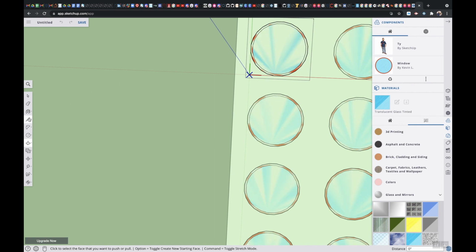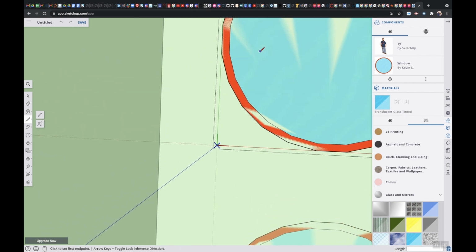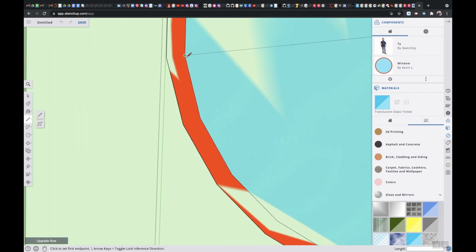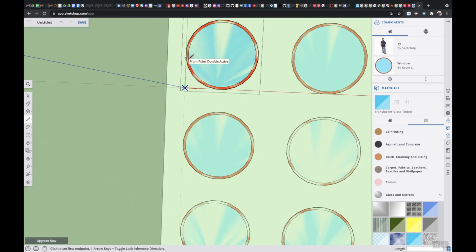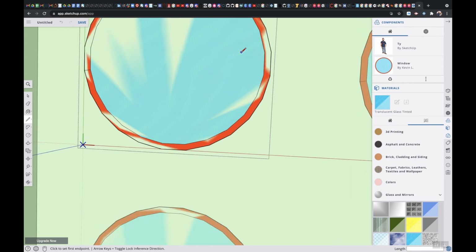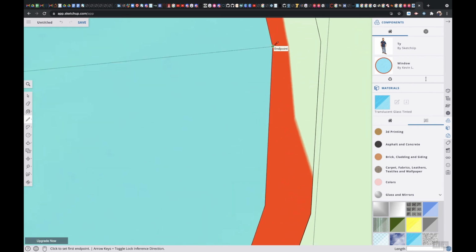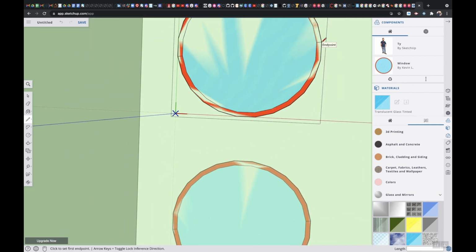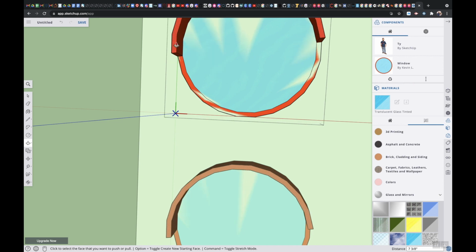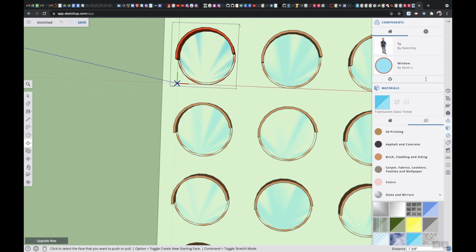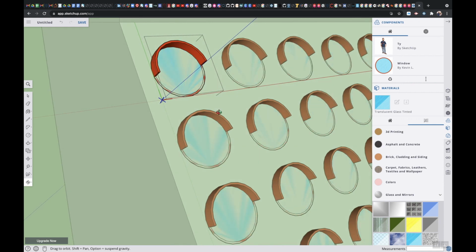Okay. It's really important that you actually grab the corners, otherwise this won't work. So zoom in. There's a corner. The corner, perfect. And I'm going to zoom in over here. Again, so we're going to go corner to corner. Hopefully this will work. I'm going to go Push/Pull. Perfect, there we go. So now we can pull that up like that. And if you notice, look, they're all being pulled up right now because we're inside of this component right here.